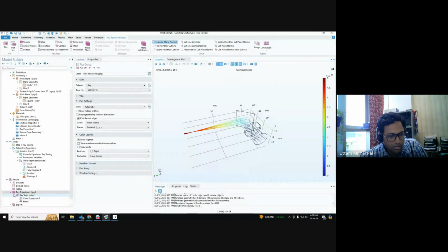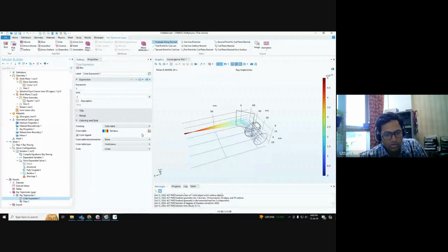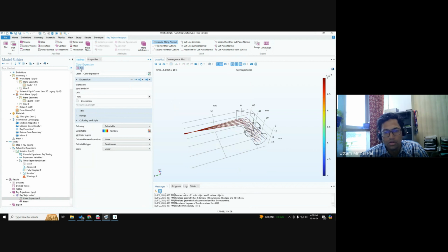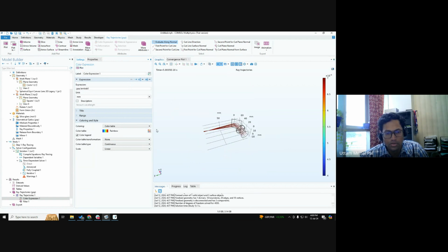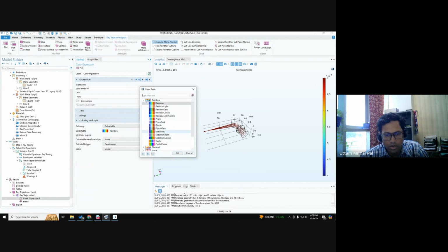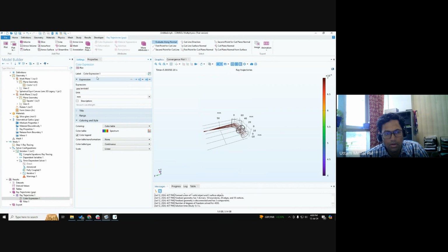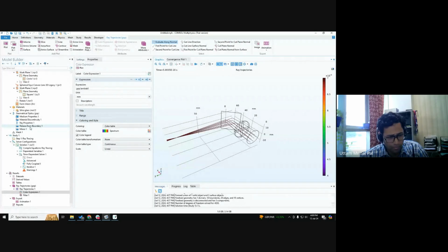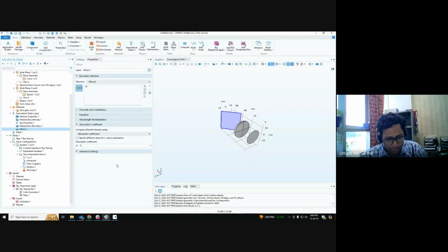You can also change this color expression to the light source that we want. So instead of an expression of t, you can actually mention a wavelength, because now we have the light source. Okay, so instead of this I can have some kind of a spectrum. Okay, so they are actually together. There's no dispersive material, so you cannot see the difference, but they are all together over here. Okay, now comes the important part of applying it as a dichroic mirror.